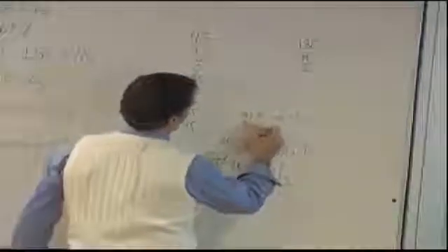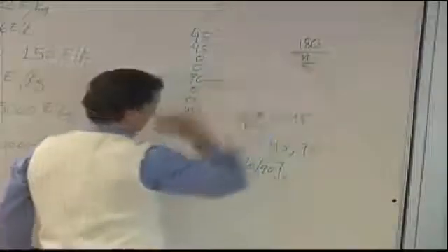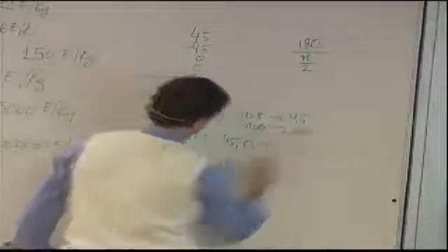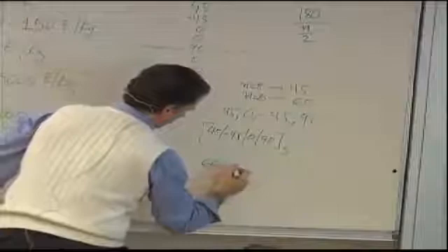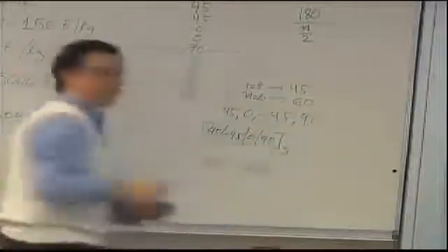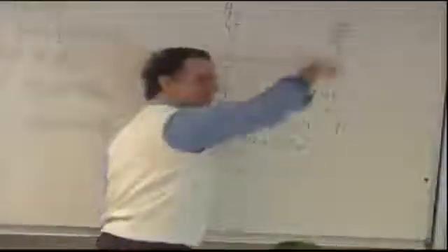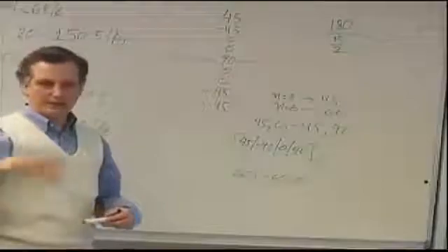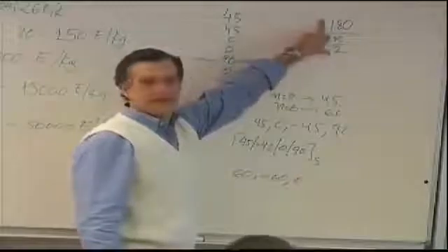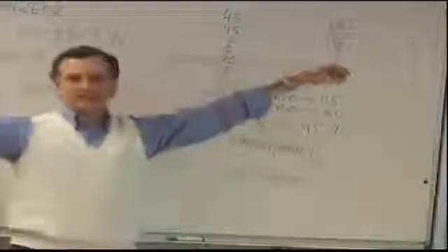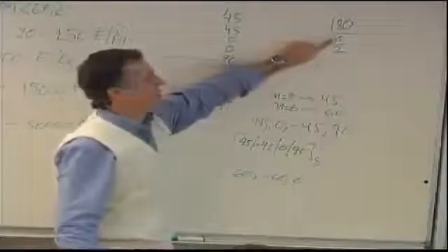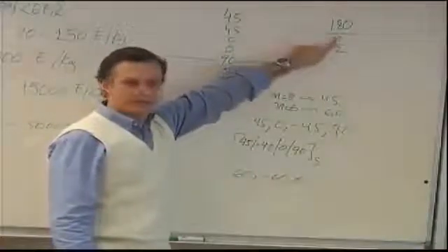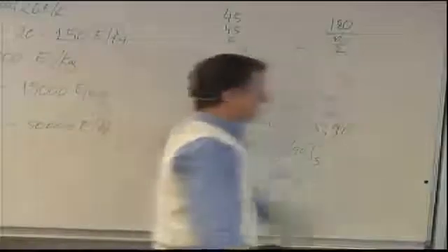If instead of n being 8, I had n equals 6, 6 divided by 2 is 3, 180 divided by 3 is 60. So any combination of 60, minus 60, 0 in a symmetric laminate configuration would give me a quasi-isotropic laminate. And you can change n to anything you want. It's just that after a while you will be getting fractional angles and so on. And if you're trying to think where I got this, 2 times 180 is 360. So I'm taking the full circle of going around, and I'm making sure that I divide it in equal intervals, and I have fibers in those equal intervals, which is the same. That's where this comes from.